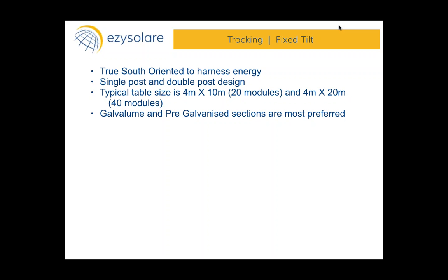And column posts, for sure no Galvalume? We won't be able to do it in Galvalume; the entire structure will fly off even while installing it. So for column posts it is 100% either pre-galvanized or hot dip. We recommend going with hot dip, and column posts should not be less than 2.5 mm.